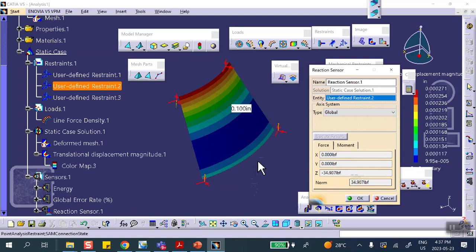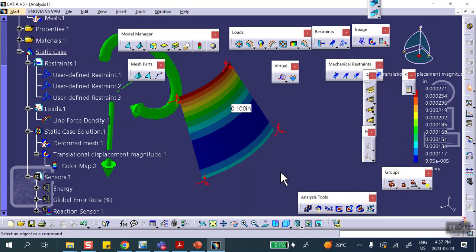This is how much force the ground is tolerating. 30.4, 34.9 pounds. And then you can divide it by displacement, you're going to get your stiffness. Or you do that in your head, 100 pounds per inch, find out what the length of this thing is, multiply it by that length, and believe me, you're going to come up with that number. Okay? So that takes care of this problem.